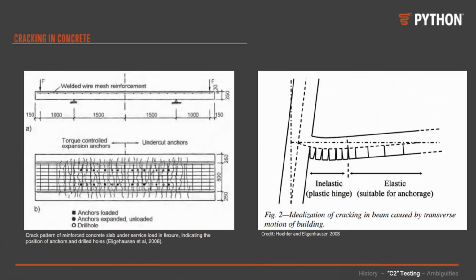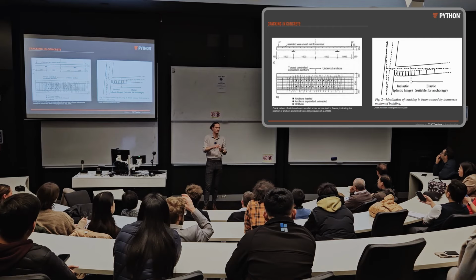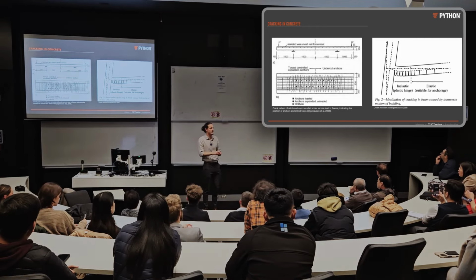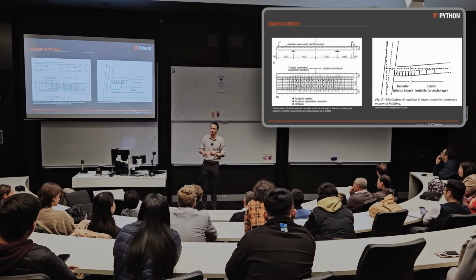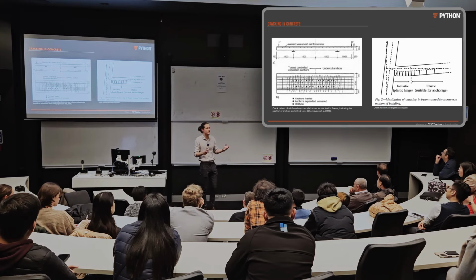This is looking at the crack widths that we allow for. Now, there are two crack widths of note, and you're going to be sick of me saying these numbers by the end of the presentation, I'm afraid. But there's a 0.5 crack width, and there is a 0.8 crack width. 0.5, these are millimeters. 0.5 millimeters is intended to represent service conditions and light seismic loading. And this is best represented by a C1 capacity.